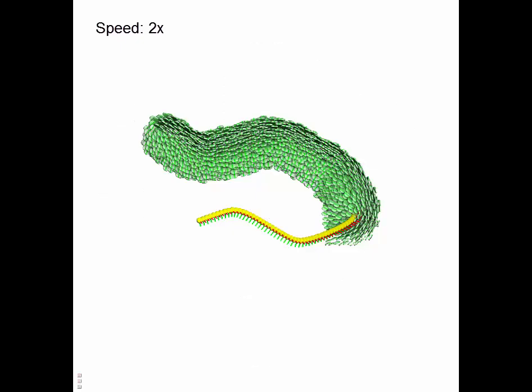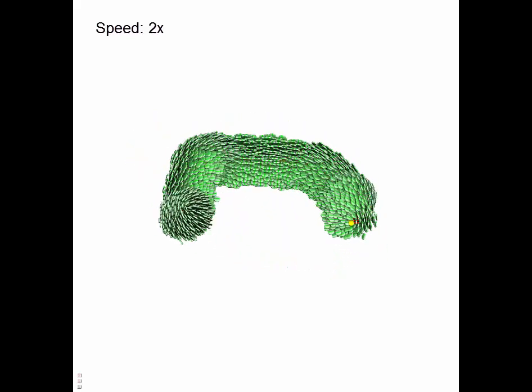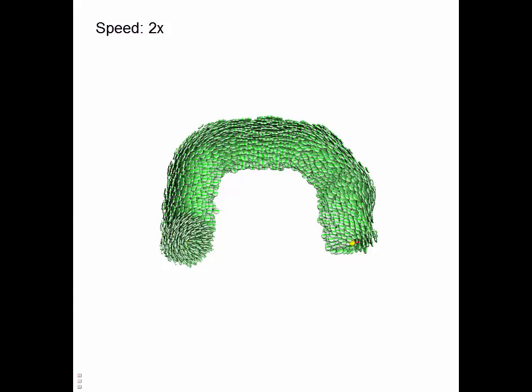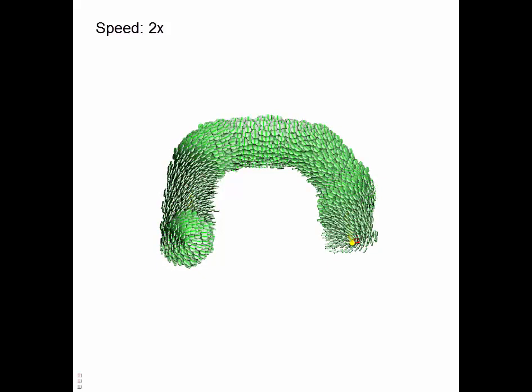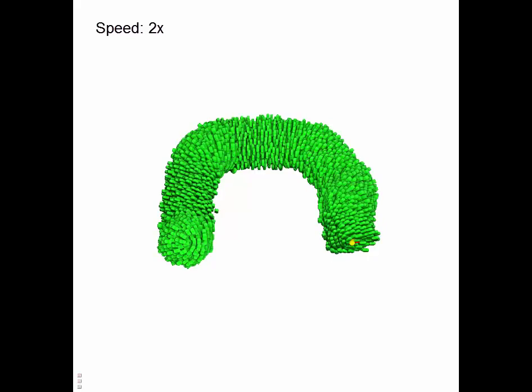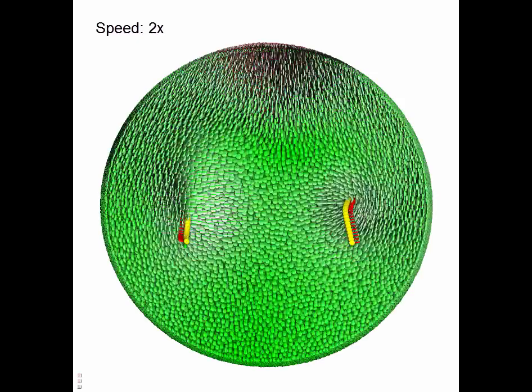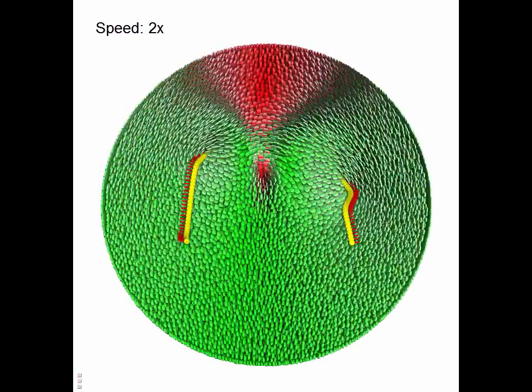By hiding the TET mesh, we can see that the system places tensor values at the vertices of a neighborhood around the curve. By using currently off-screen controls, the user can edit the properties of the curve, such as rotation or the tensor mode. Once the desired constraints are set, the tensor field can be filled in for the rest of the volume.